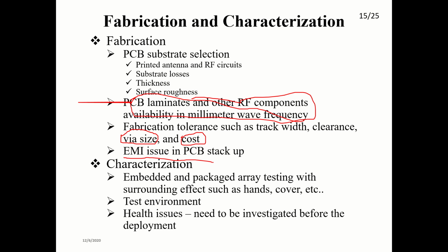Next is the EMI issue in PCB stack up. EMI is a very serious issue, because here signal integrity and power integrity problems arise. You can see in several job portals that there are plenty of requirements for signal integrity and power integrity engineers. Why? Because when you stack up multi-layer components and place several components together, all will talk to each other, intentionally or unintentionally.